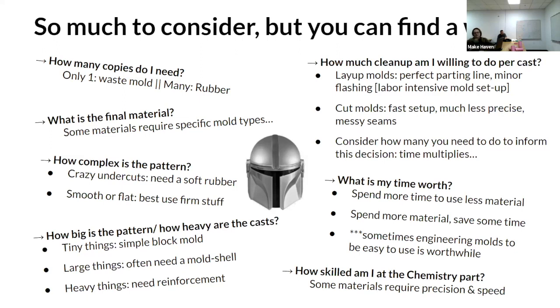Something for molds that's just really fun: these are molds to make rubber feet for the vibration table that I have downstairs. I made a couple of 3D printed ones. The castings were soft, so these were rigid, and then I used alginate to copy them so that I could make more. So this is a plaster mold. You can use it as a technique in your wheelhouse to transfer things into new materials and speed up your workflow when you're prototyping or doing anything else like that. If you get a chance to see these, it's something I do a lot, moving materials from one to the next.